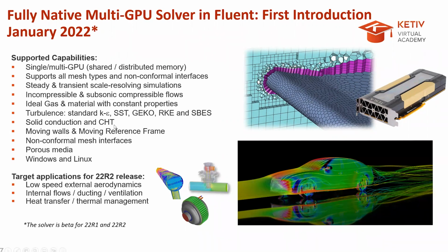Solid conduction and conjugate heat transfer are also supported in the current multi-GPU solver. So if you're doing internal simulations, HVAC simulations, those types of problems are well supported by the native GPU solver. Moving walls and moving reference frames can also be done. You also have the ability to do non-conformal mesh interfaces and porous media zones in the GPU solver today. This GPU solver is supported on both the Windows and Linux platforms.